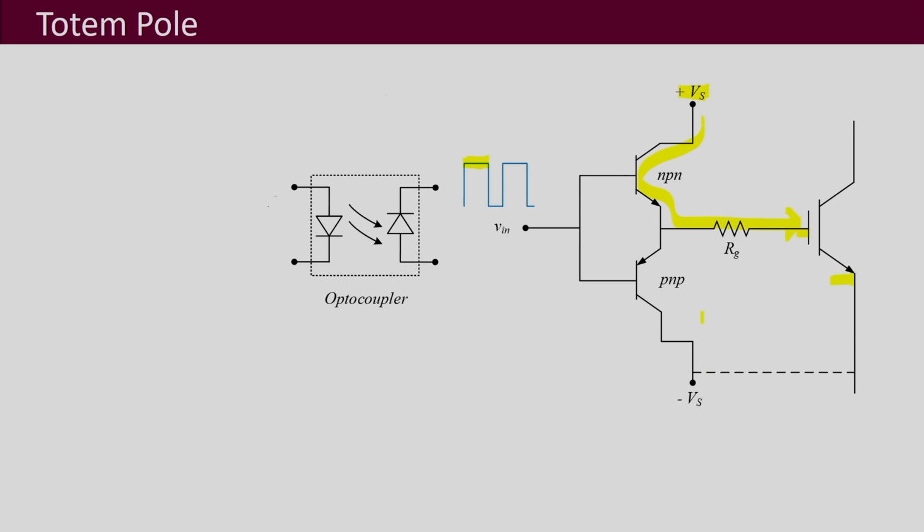Okay. And these can be transistors which have the ability to supply the current that is required by this gate emitter region. Then next, when this gate pulse goes low over here, at that time what happens is that low means PNP will start to conduct and NPN will go into cutoff. So if PNP conducts, what is the direction of the current going to be? Like this.